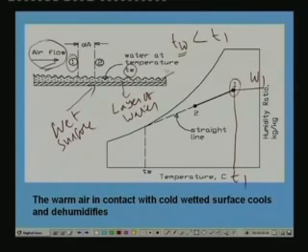When you have a wet surface at temperature Tw, a concentration boundary layer develops near the wet surface, and air in the immediate vicinity of the wet surface will be saturated. That means in the immediate vicinity of this wet layer you have a saturated water vapor layer, and since this temperature is also the same as Tw, the condition of that layer will be represented by this point.